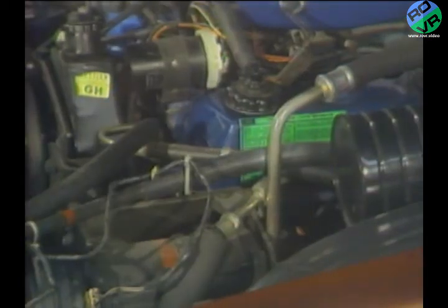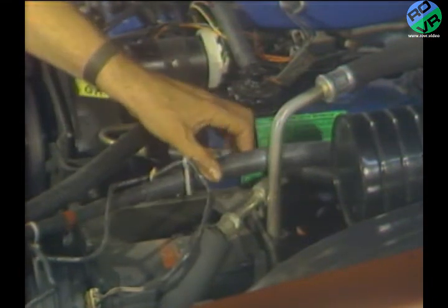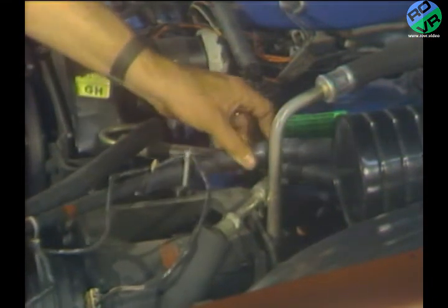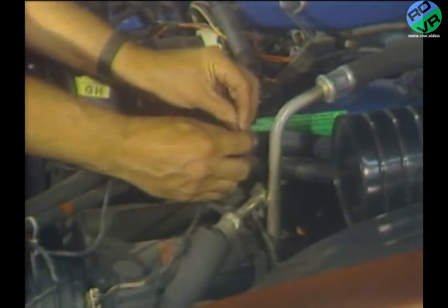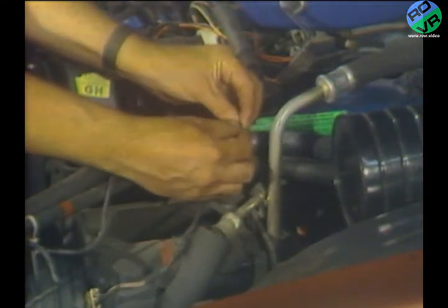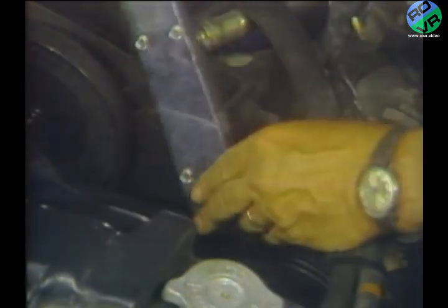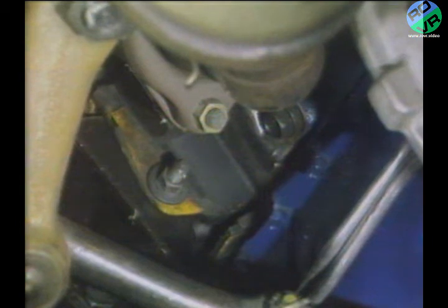Sometimes an air conditioning or power steering hose will vibrate against inner body panels or other under the hood components. These hoses should be adjusted and rerouted properly. Loose bolts, such as this one on the air conditioner bracket, should be torqued to specifications listed in your shop manual. Other engine accessory NVH problems can be caused by loose or misadjusted power steering pumps or water pumps.